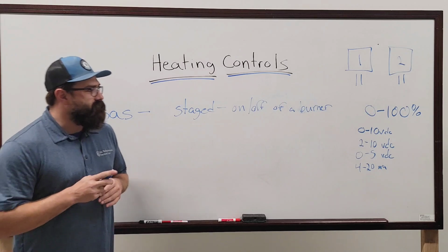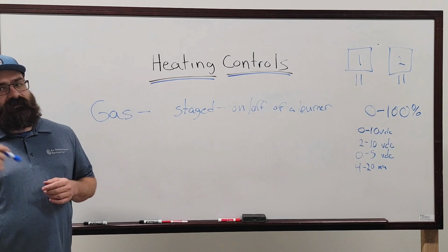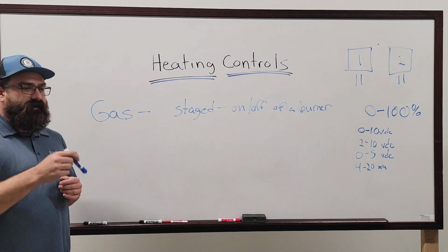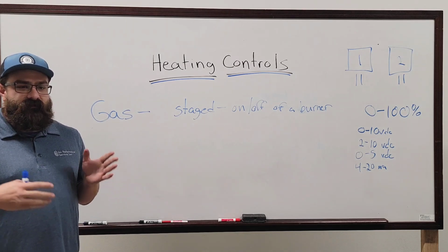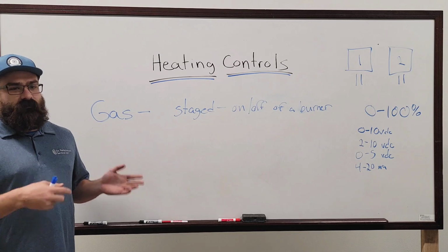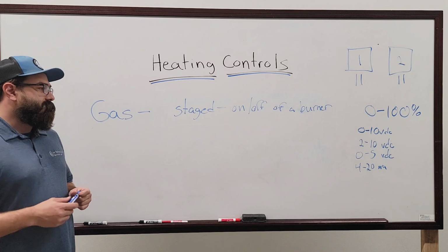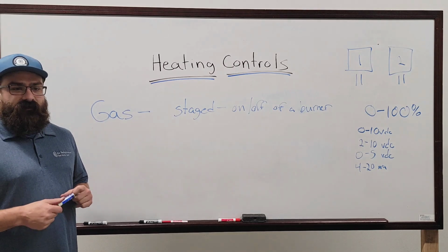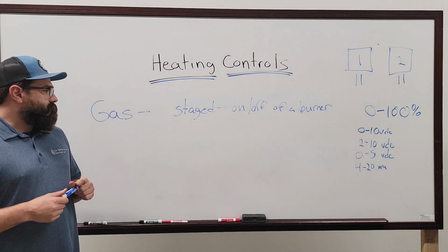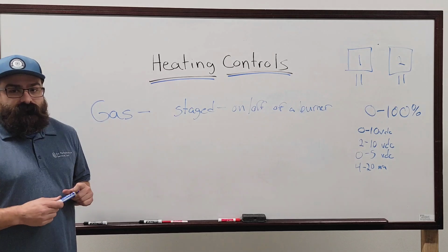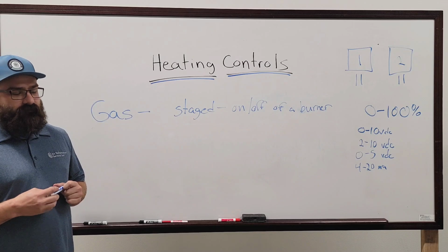Gas systems tend to start the heater first, then the fan, and you shut the heater off and then leave the fan running. It's to keep you from getting a big blast of cold air when the fan first kicks on and the heating element's not running. And then it's also to remove the latent heat from the burner system once it shuts off. Kind of just a longevity of the system type control. Yeah, and gas is pretty simple. Just turn the valve on. Pilot light, all that stuff's built in.